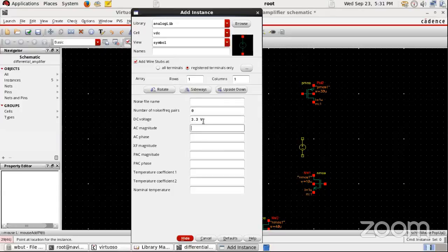Okay. The bottom two should have an identical W/L aspect ratio, and the upper two, which we use as a current mirror, should also have an identical aspect ratio, right? Now since it is PMOS, we are just having the width three times that of the NMOS, 30 micron. That is one of the reasons.